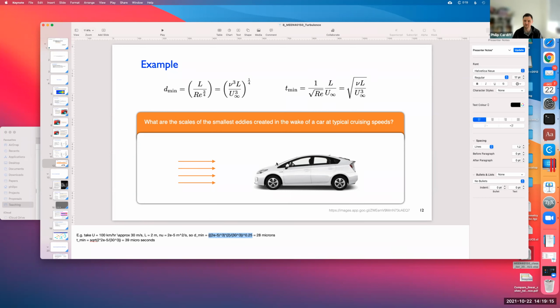If we were trying to model flow past a car, and we want to describe these smallest eddies, so a small rotating piece of fluid, for one rotation you probably need 4 cells, because you can't have a rotation in a single cell. You only have one velocity. So you need at least 4 cells to have the velocities going around. So divide that by 2, and about 10 microns would need to be your mesh resolution. It should be obvious to you that's prohibitively expensive.